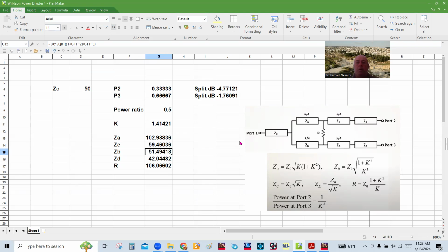But when you don't have equal power, let's say for instance I want to design this one so that I have 1/3 of the power on this port and 2/3 of the rest of the power on this port. Of course, we're assuming in all these cases that we're lossless in these equations, which we are not, but we're assuming the losses are going to be symmetrical between port 1 and port 2 because the copper lengths are the same.